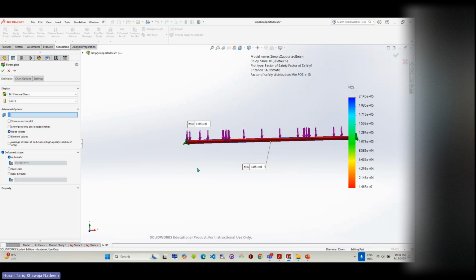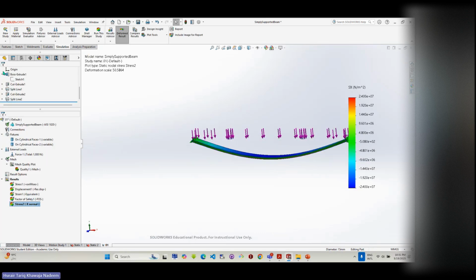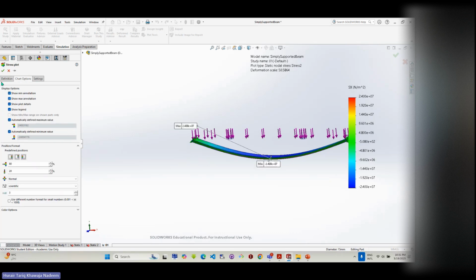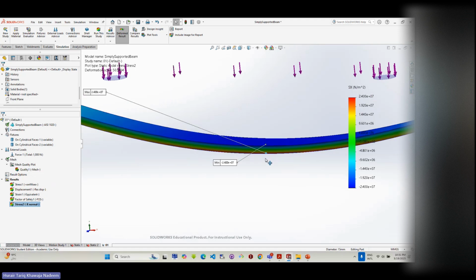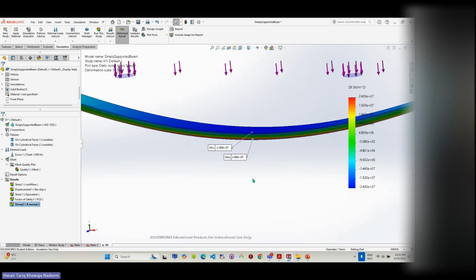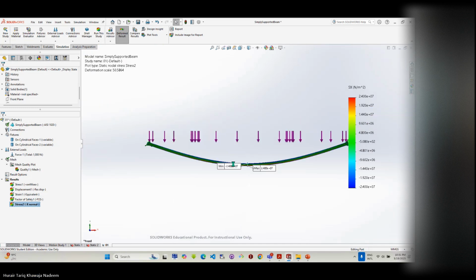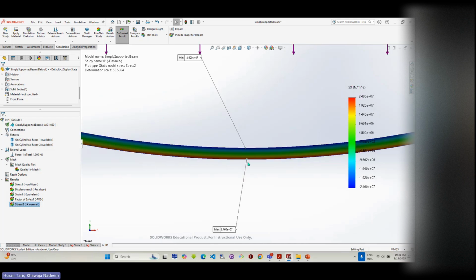Okay, let's see how it works. I click on this one, and this is X normal, and click edit definition and go to chart properties and show maximum and minimum. So what is it giving me? A minimum value and a maximum value. Let's move it down like this. This is nice, isn't it? Okay. What does it tell me now? This top is minimum. It's telling me that it's at the center, isn't it? And this is maximum. How much is the value? Maximum is 2.4.